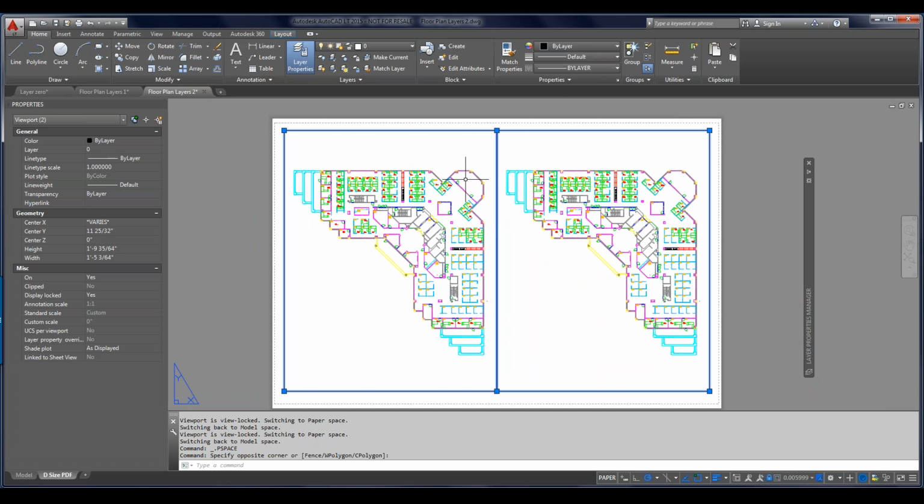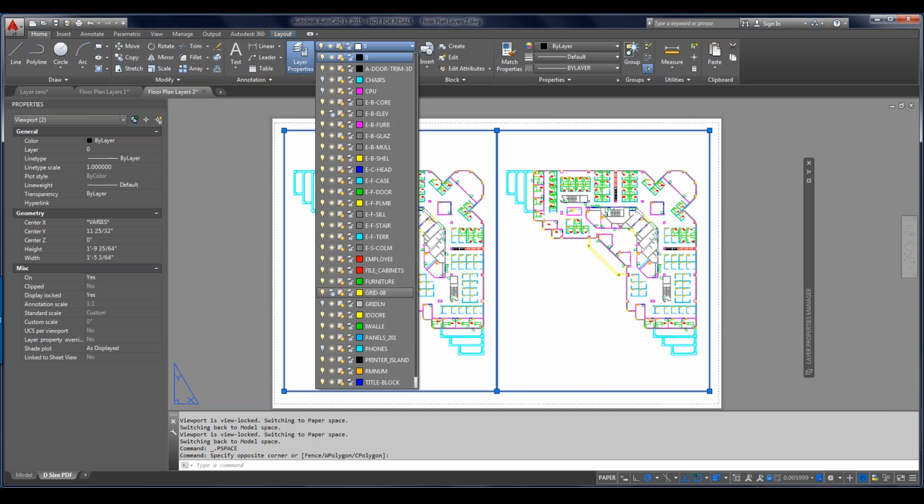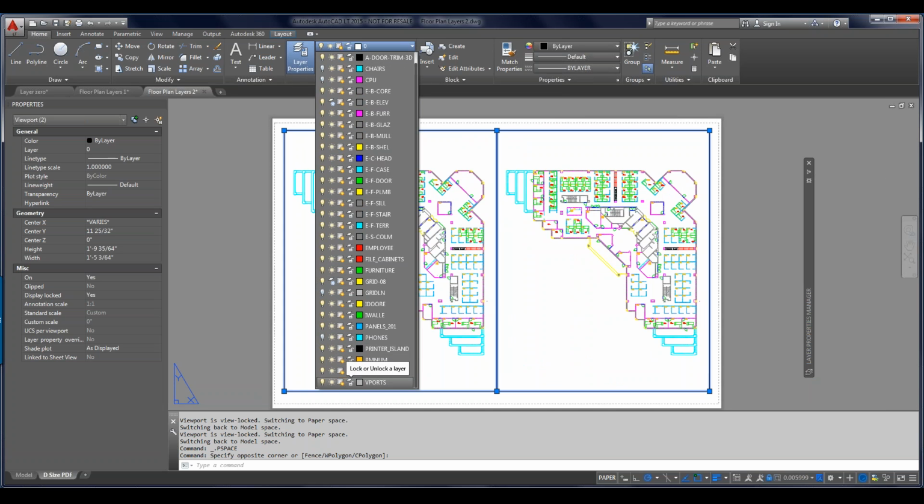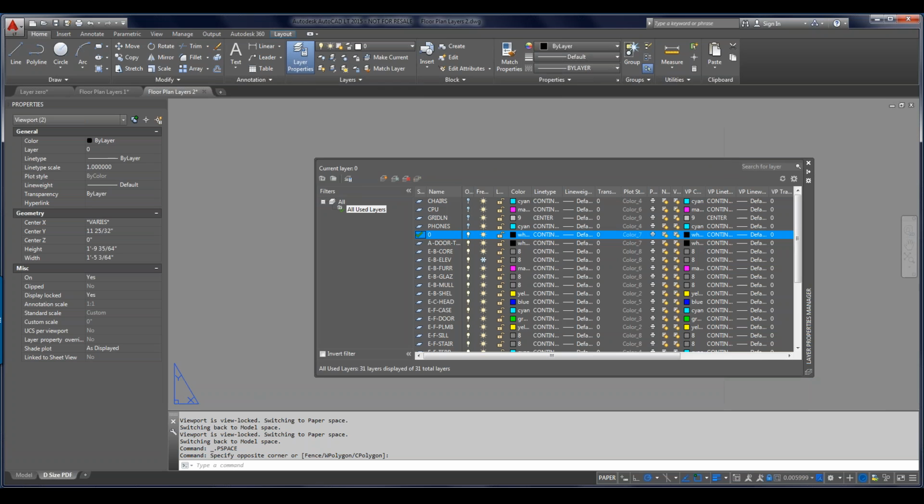It's an organizational standard. Personally, I create a layer, and I call it Viewports or Viewport or VP, something like that. And I do need to, whoops, kind of zoomed out there. I do need to go in here to do this. There is this icon here that is a printer icon. And right now, the way it is, it's showing me it is set to not plot.